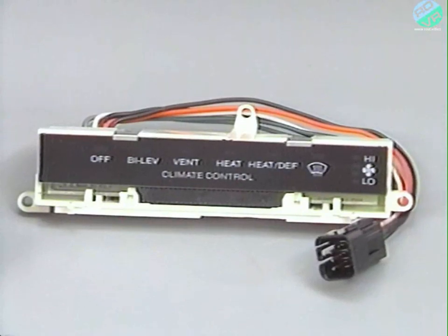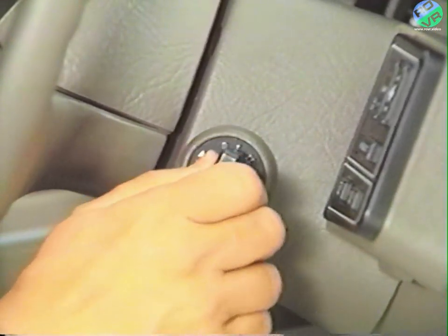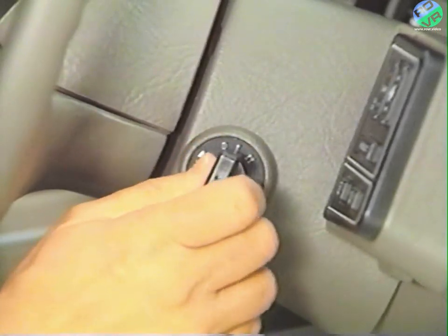The primary reason to enter self-diagnostics is to determine the cause of a fault indication on the display module. On heater-only systems, the display flashes a mode indicator for 5 seconds to indicate a fault. On both systems, if the cause of a fault is eliminated, the ACM will discontinue the fault indication after 60 cycles of the ignition key. Disconnecting the battery will also discontinue the indication.